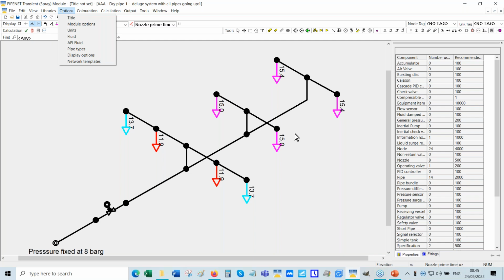So, when you have bigger pipes, in steady state, typically it's better because it's less friction loss. But when you're calculating the discharge time, it is not always an advantage to have big diameter pipes because they take longer to fill up. Keep this in mind. The second point you have to keep in mind is that the most remote nozzle is not necessarily the last nozzle to discharge.